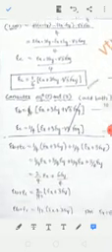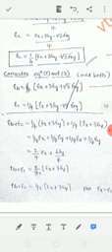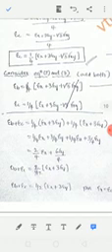Again you have to substitute 120 degrees in that equation, take the LCM, and simplify. You can get epsilon C equal to 1 by 4 of epsilon x plus 3 epsilon y minus root 3 gamma xy. Now consider equations number 2 and 3 and add both. Ultimately the root 3 gamma xy and minus root 3 gamma xy are both cancelled. Now you will get epsilon B plus epsilon C.